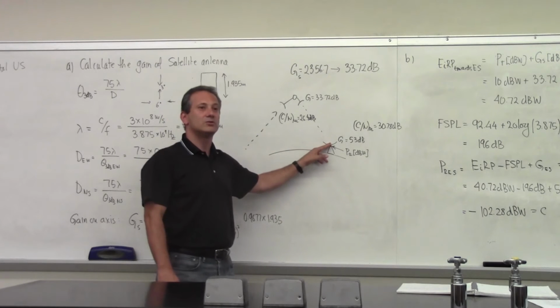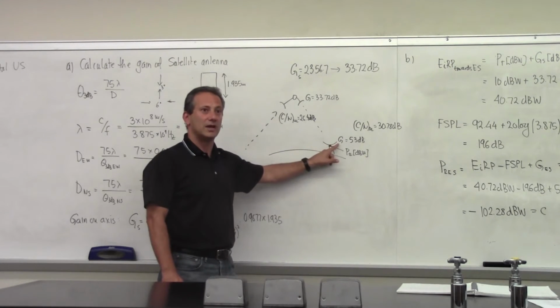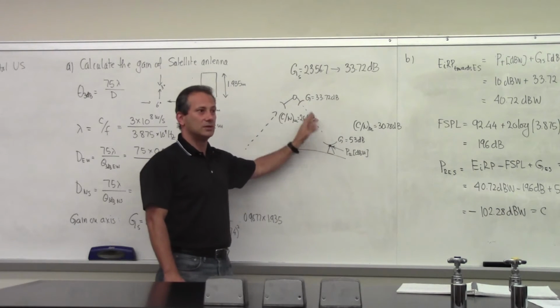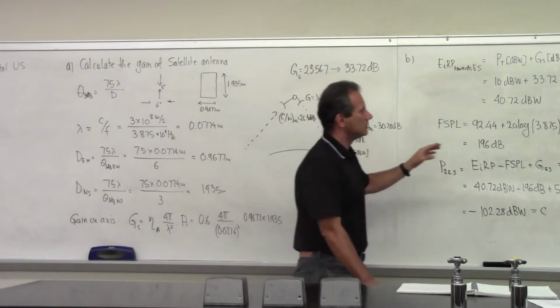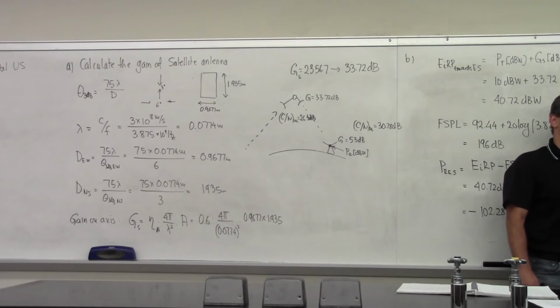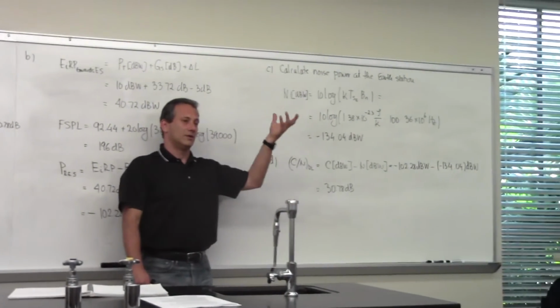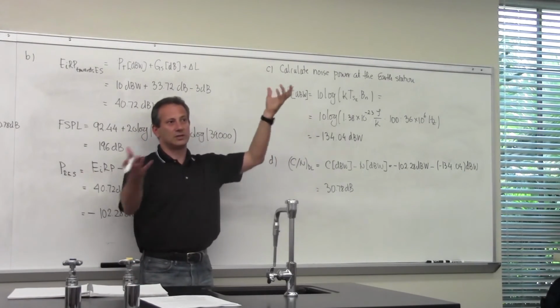The C to N has to degrade because there is some additional noise at this point. But the signal plus noise that comes from the transponder, by the time it reaches the earth station, is more than 30 dB above the locally generated noise, more than 1,000 times stronger. So you have an elephant and a mouse, and combine the two is just an elephant still, right?